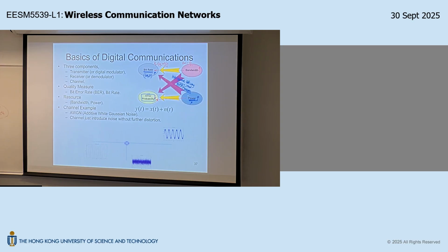On the other hand, if you look at 16 QAM, when you switch between the points due to the input bit combination changes over time, if you go from here to here, you will see different amplitude as well. So the amplitude will fluctuate more, over a larger dynamic range, for 16 QAM. Is that okay? So that's why we have this issue.